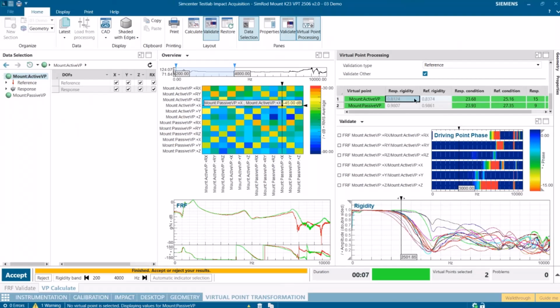Now, the reason why this happens can be because the structure, the jigs, are not made rigid enough, but what is also possible is that we didn't do a good job of pasting our accelerometers exactly where we said they would be on the CAD model. So there is kind of a mismatch between the virtual and the physical instrumentation.